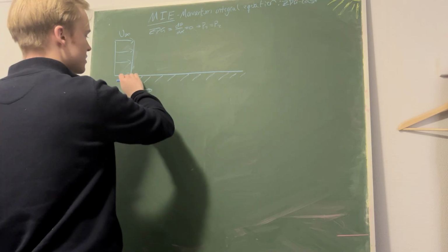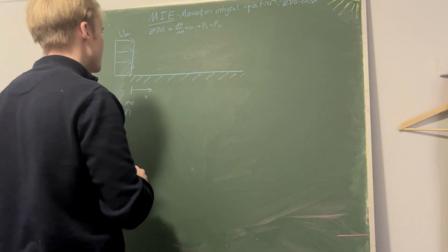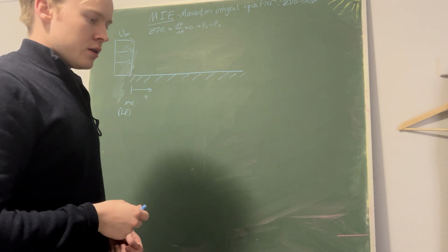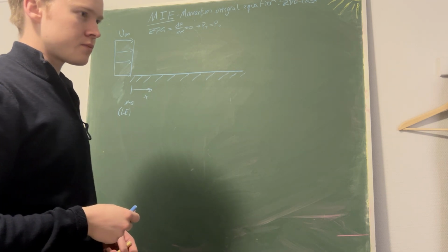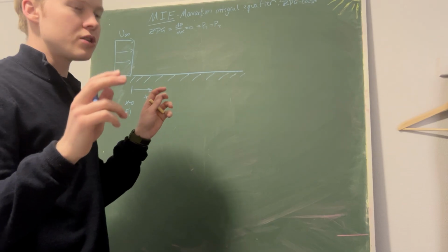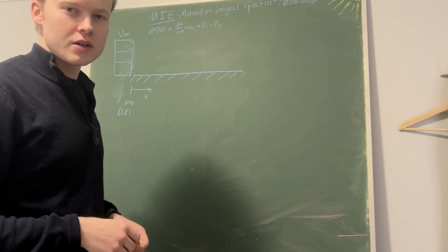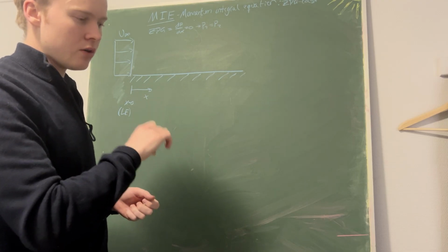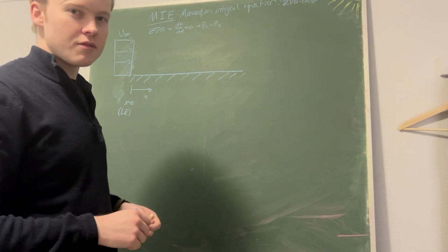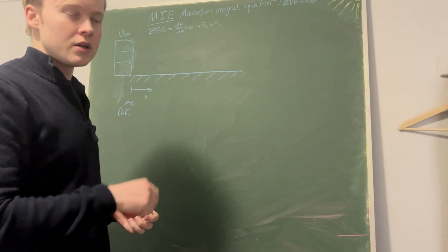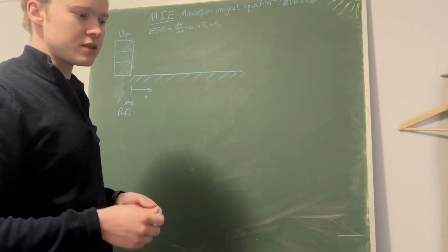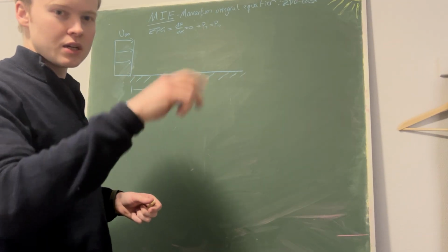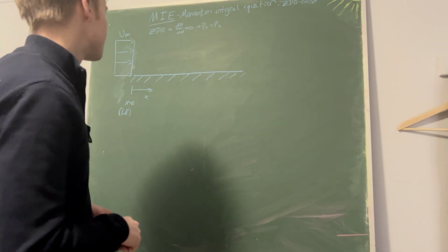And then as the flow evolves over this, the boundary layer will grow. And the boundary layer is basically, you can say it's not an imaginary thing, but it tells you how the velocity field very close to the wall is developing. In a way, it's like a thickness, but it doesn't tell you the shape. It's only a thickness that grows with x.